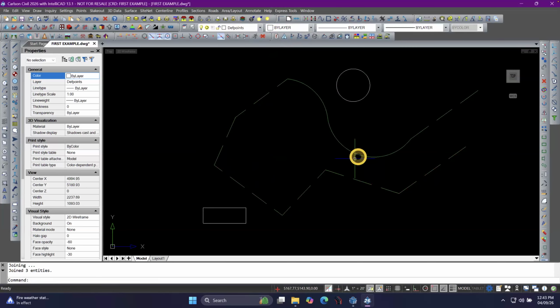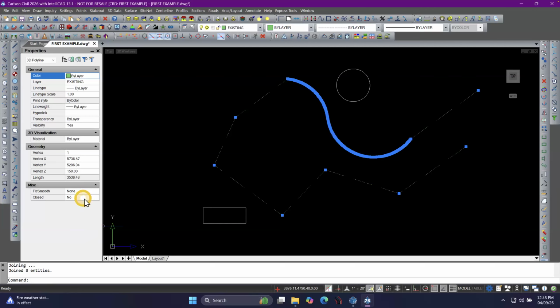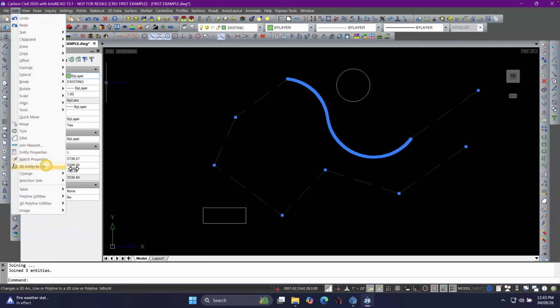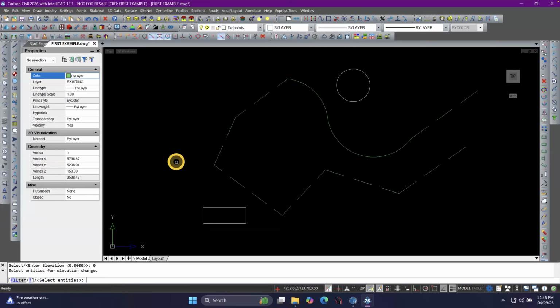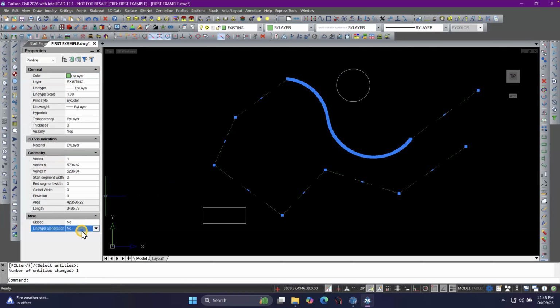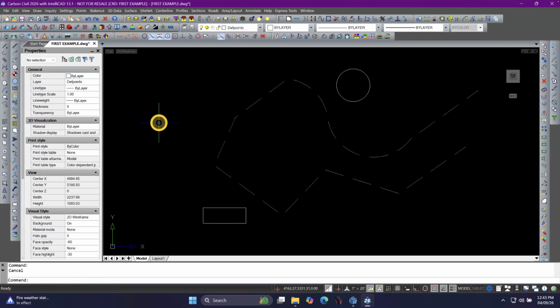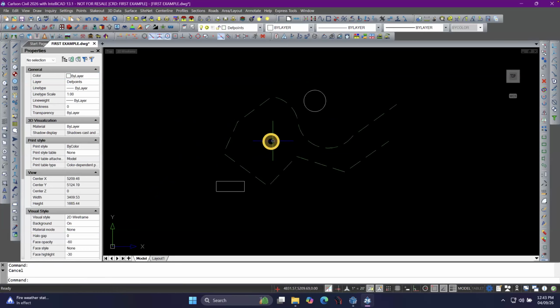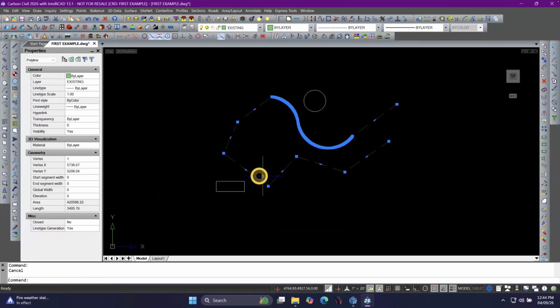And since they're connected, they're now all part of that. It's a 3D polyline. Yeah, there we go. The line types all work out. So there's a case where if you needed to connect something together, they have to exactly hit on those corners. Okay, so that's why entity snapping is going to be important.